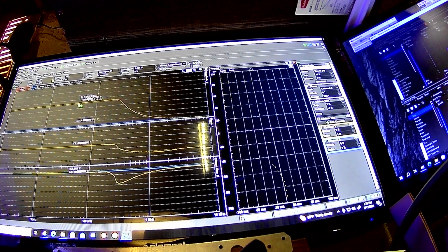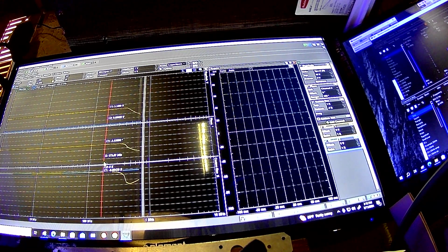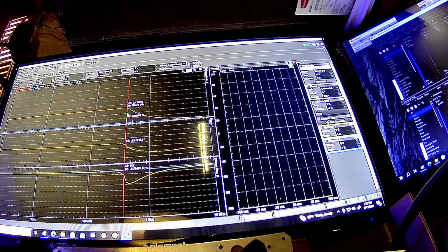And if I take it down to 1 volt, that's like 2 volts peak to peak. So let's see what its power bandwidth is. That's about 390 kilohertz or so, generally where it starts to diverge. Its corner frequency would probably be about 400, but visually, what's pleasing is this point where it starts to fall off. But that's a way you can test your power bandwidth with the Analog Discovery, as opposed to just testing it with 1x probes.